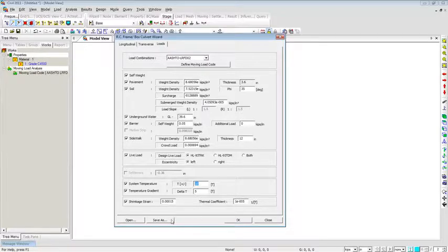The reason you would like to save this wizard file is that when you want to create similar bridges again and again, let's say you have a library of bridges that you want to generate, then you can save these wizard files and then open them later on in a different model, make some changes here and there, and just hit OK and generate the bridge. So in this way you can do all this hard work of entering the data once, and then later on you can save time on every second bridge that you are making. So this adds to your productivity and increases your efficiency.